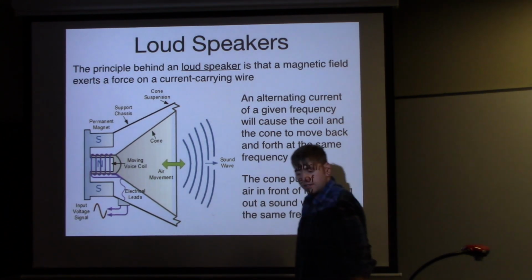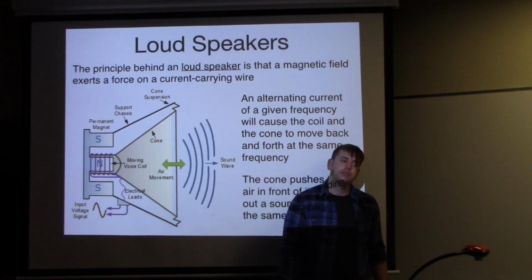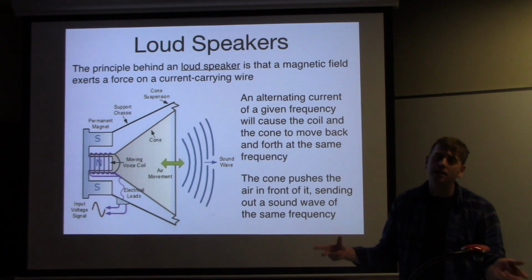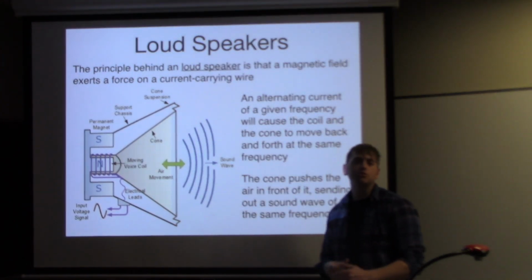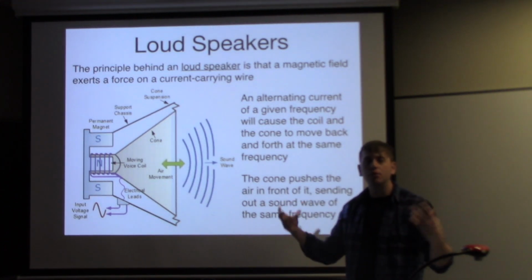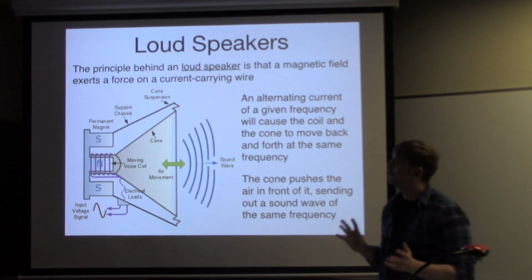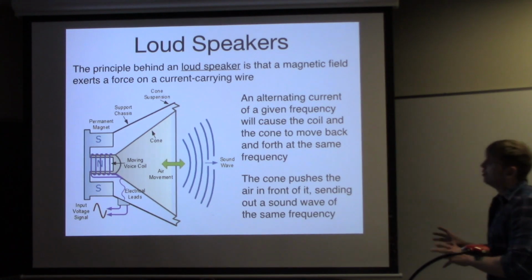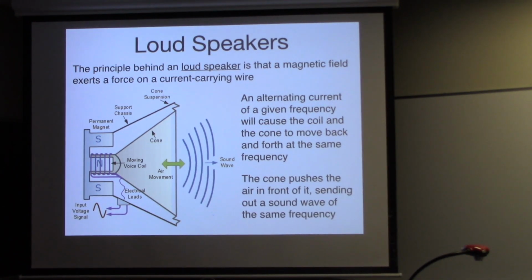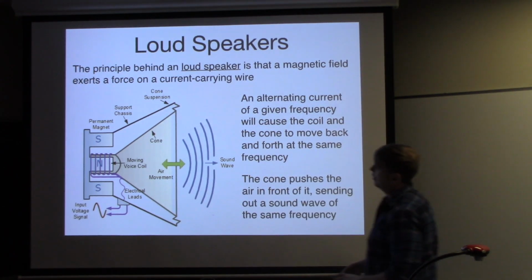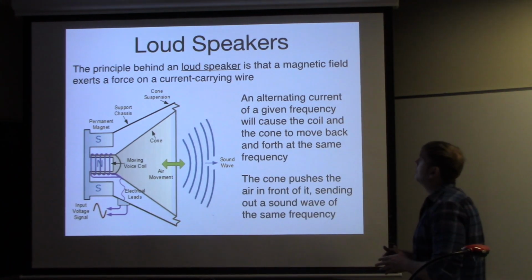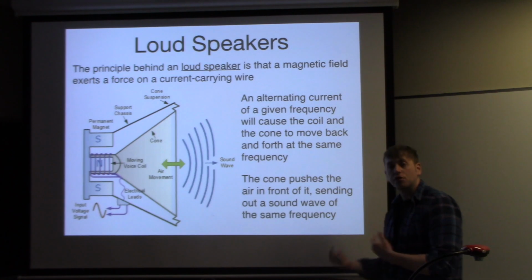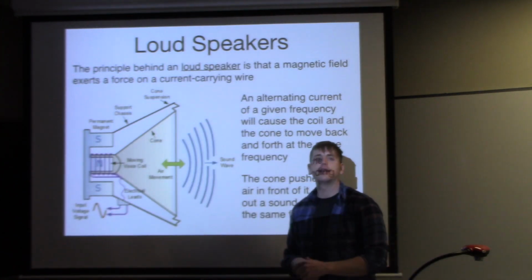The next thing is loudspeakers. And really, this applies to anything from speakers in your car to your home audio system to in-ear headphones, whatever the case may be, any kind of loudspeaker. The principle is basically this. If we have a magnetic field, it will exert a force on a wire that carries a current, right? We saw that way back at the beginning of this lecture.